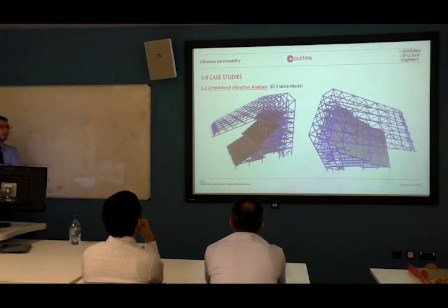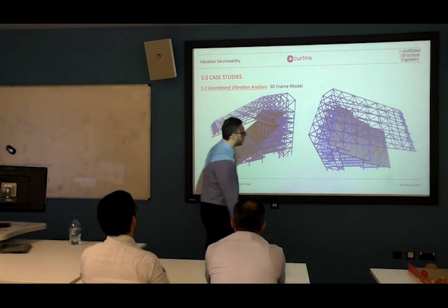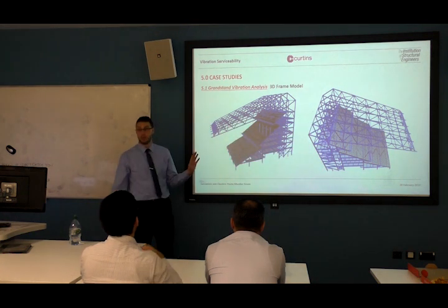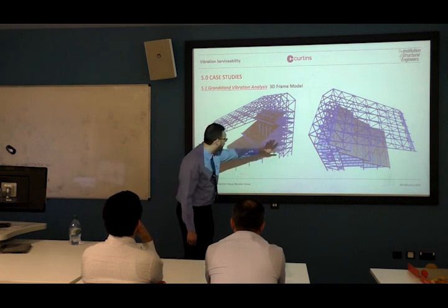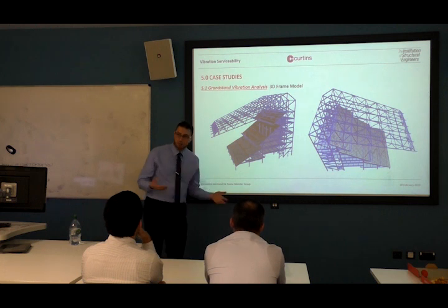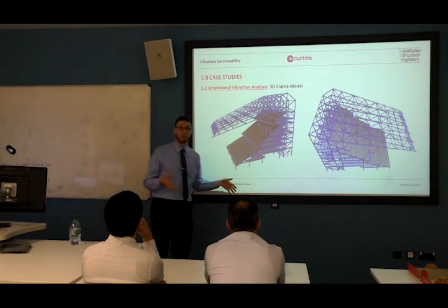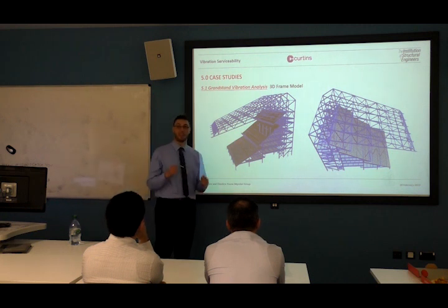Now we had to do a bit more and develop a very rigorous 3D analysis, 3D model. So you can see here, we've had the roof bracing here, we've added the seats as they are to the grandstand, we've added the concourse and the floors here, thinking about diaphragm, you know. This one took me about a month to develop the model only. And also every single person now is modeled as a spring mass dashpot system.